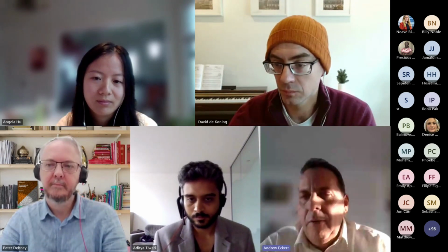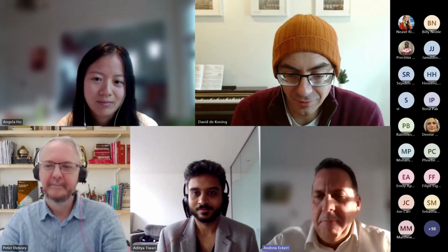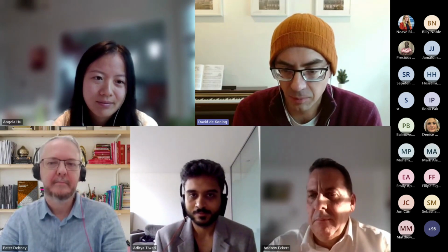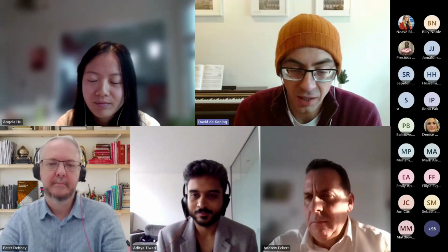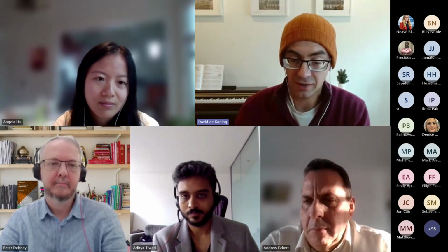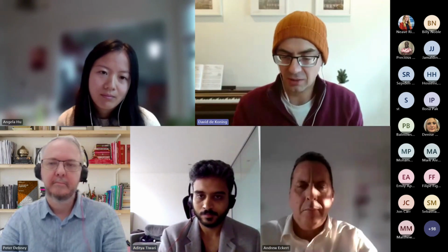Great. Next question is, can you plug GSA into Revit for analysis and design? And again, I guess that's an absolute yes. Over to you again, David. Yeah, GSA comes with a Revit plugin that allows you to transfer back and forth from Revit into GSA. And as Angela spoke about with the design layer and the analysis layer, you can just bring your BIM model into the design layer, and then you get control over how that gets meshed and how that gets analyzed. So rather than trying to do structural analysis in Revit, we say, just bring the BIM in, and now you can be in control as a structural engineer.